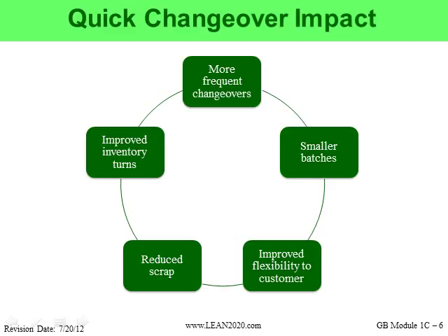The other choice that we had is we could put that 18-inch wide film through our laminator with the wider film on there. So we could run an 18-inch board through the laminator with 24-inch wide film, but then we'd have to trim the edges. By trimming the edges, we'd potentially induce some film chips into the process, which could create some quality issues. So we really didn't want to do that, but that was a shortcut that we could employ. Wasn't the best case scenario, but it was another way to again, run our process. And one of the reasons that we would do that is because we were horrible at changeover.